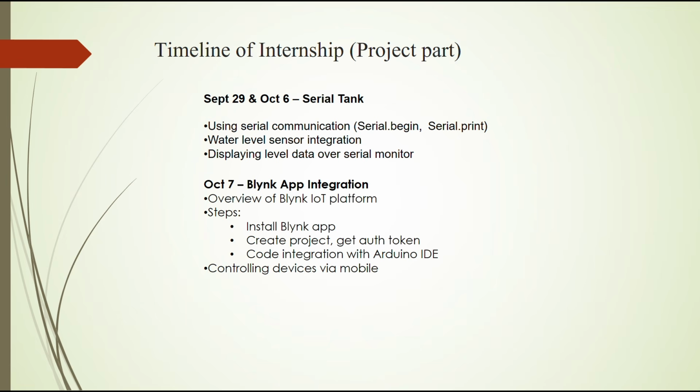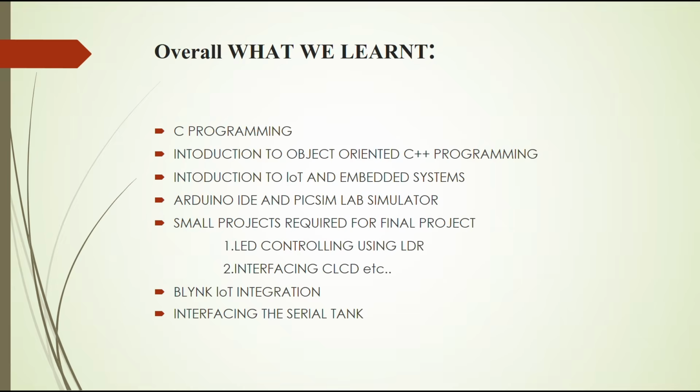Then we learn about Blynk app integration. How to integrate the Blynk app with this project. Like first we have to install this app, then create project, then generate the authentication token, then use this token in code integration with the Arduino, then controlling devices via mobile.